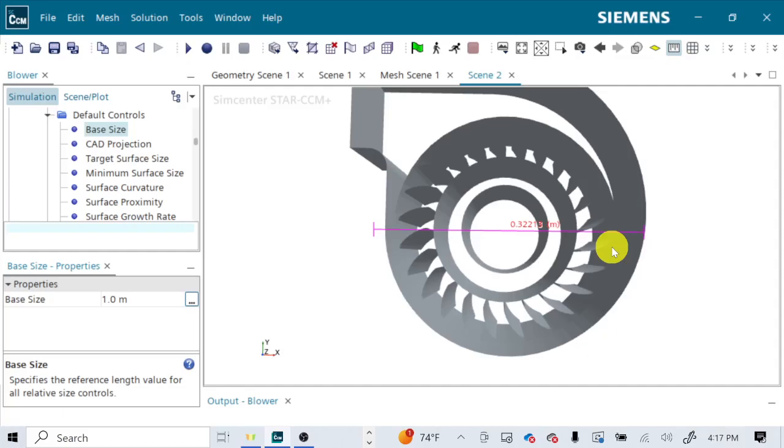in that general neighborhood, just based on the rough size of this thing. A half centimeter will give us 60 cells across, roughly, right? Which is probably about right. It might not quite be enough, but it also might be. So somewhere between about a half centimeter and 2 millimeters would be a good estimation. I'm going to start with the bigger size, a half centimeter, because if we mess it up, it won't take forever for it to mess up.